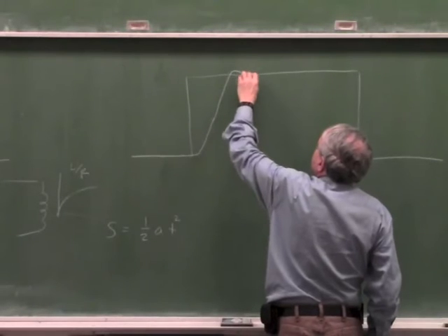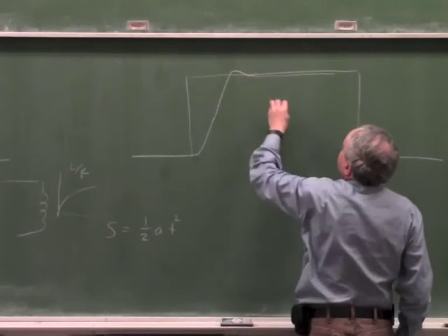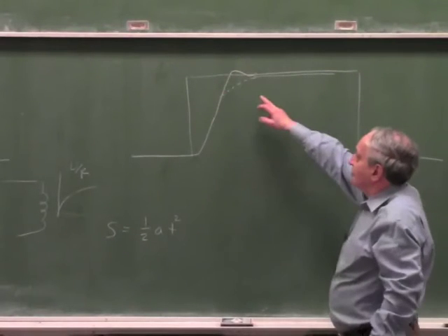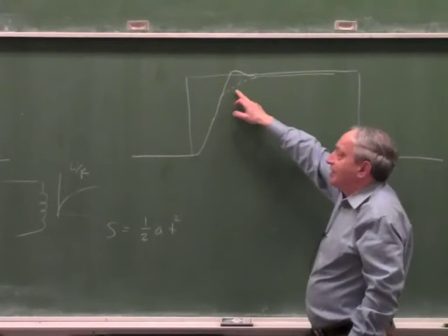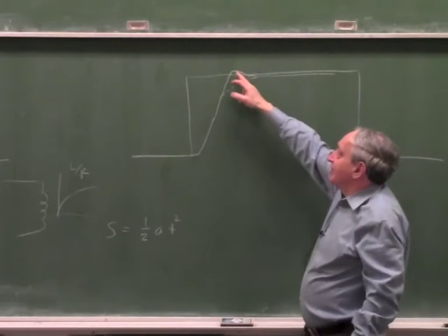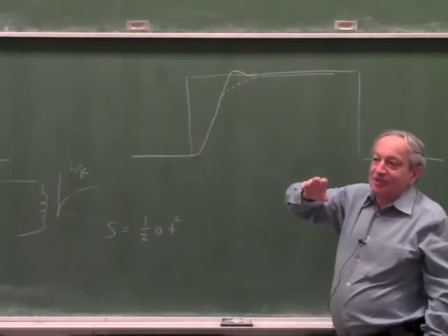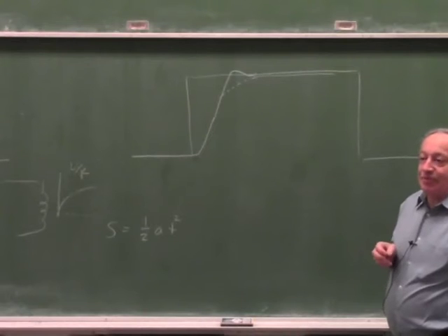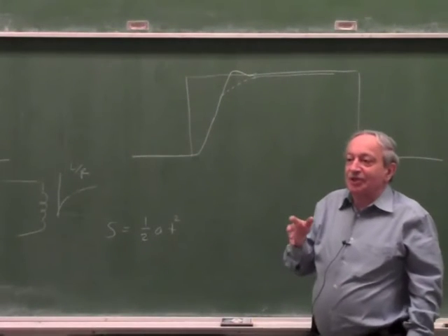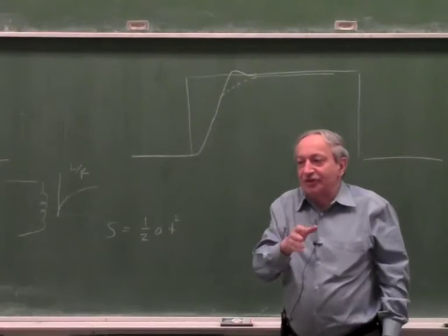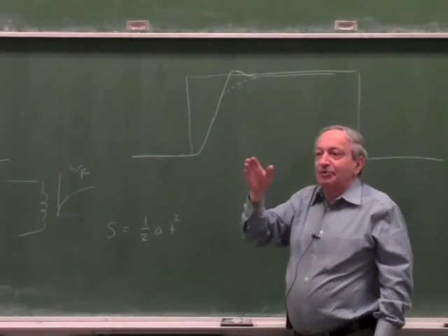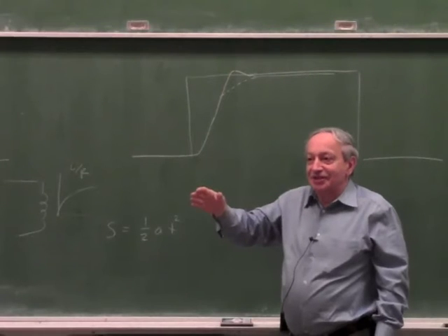And it settles, we'll talk about this too. This is a settling error. This can be like this or can be like this. This depends, of course, on the servo design. If it's critically damped, if it's underdamped, and it's not always that this is better or this is better. Sometimes it depends on the servo. For example, if you have a servo which has to deal with a lot of stiction and friction, maybe it's better to use this curve, because if it went over and a bit back, for sure it reached the target.